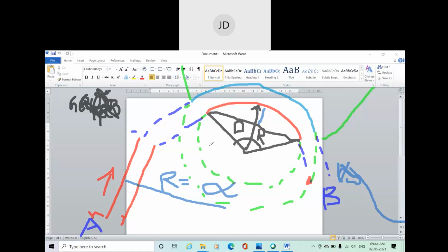So that means the radius of the straight curve, what is the radius in a straight curve? Infinity, and it slowly decreases from the value infinity to the particular design radius of the circle. So we need to reduce the radius from infinity to whatever value, suppose R dash, of the radius we need to provide, but we need to decrease the radius, not directly, gradually. That means it is gradually going on decreasing.